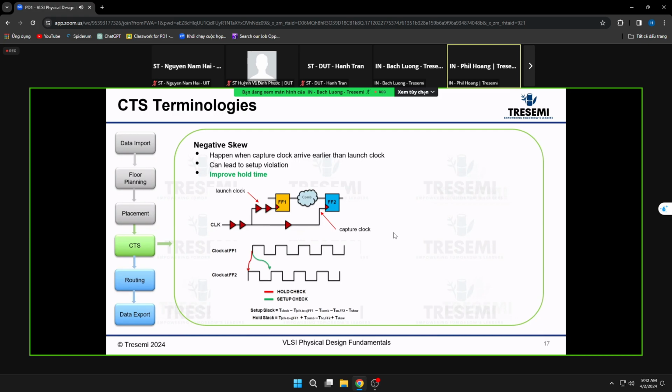So in this clock path, you have the clock with 2 buffers on the left. Each of these gates will have a delta delay because of OCV, right? CRPR means that since these two are common, in the calculation of these different paths, the delta OCV on these gates is removed.